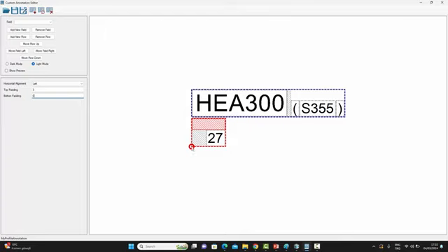But you also want this anchor to be over here in the middle, because that's where you want the line to pass from. So if you want to take this anchor in the middle, then what you do is basically you come to this general area which represents the entire thing, and there's something called the anchor row index. If you change that to 1, it'll move. It could be 0, 1, or 2 depending on how many lines you have. 0 means like the bottom, and then 1, and then 2 maximum. So if I give it a 1, then the anchor point will become the center, and then we have a little gap in between them. So these little tricks allow you to create all sorts of combinations you want with your custom annotation.